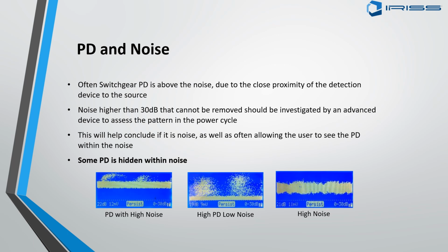Inside the equipment. So just because there's noise doesn't mean that we won't be able to isolate out the fact that there's a partial discharge event in fact occurring inside the equipment. So don't let this noise thing worry you. We have algorithms embedded in the hardware and the software that differentiate out the noise by looking at where these pickups of the transient earth voltages are happening in the voltage waveform of the equipment to which we're connected.